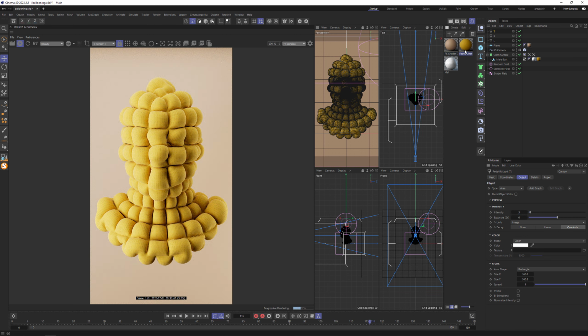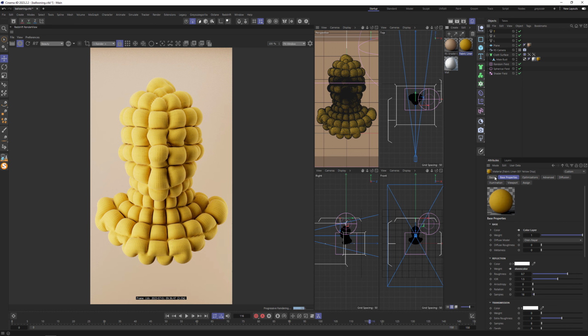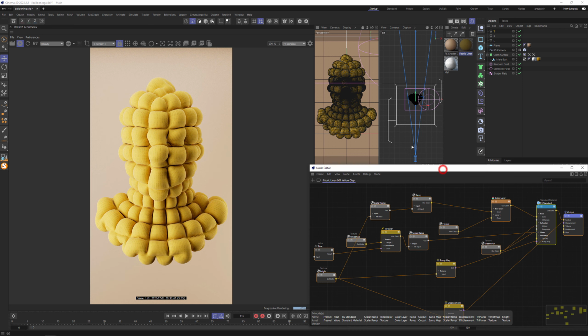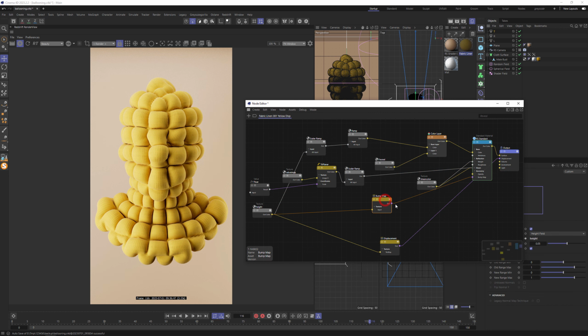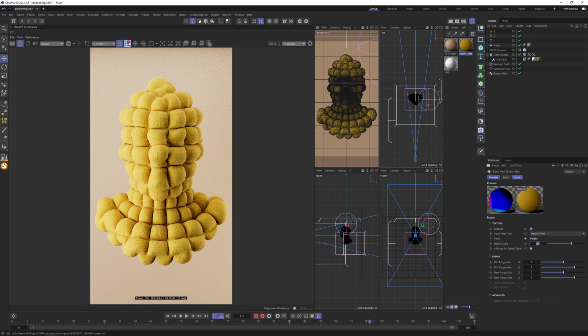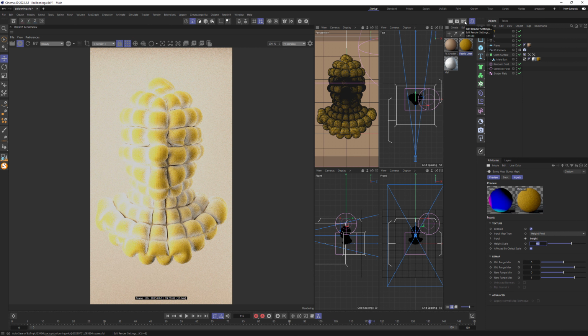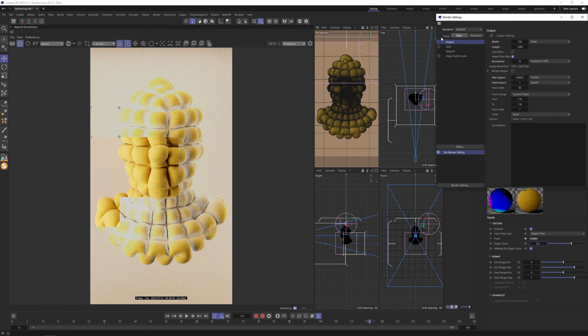Good preview. And in shader, I will go to node editor and increase the bump map because we have different scale than the preset. And I want our fabric to be more noticeable and visible. Beautiful, maybe 0.5 for the final result. Great. Checking buckets. Few tips for improving render speed.